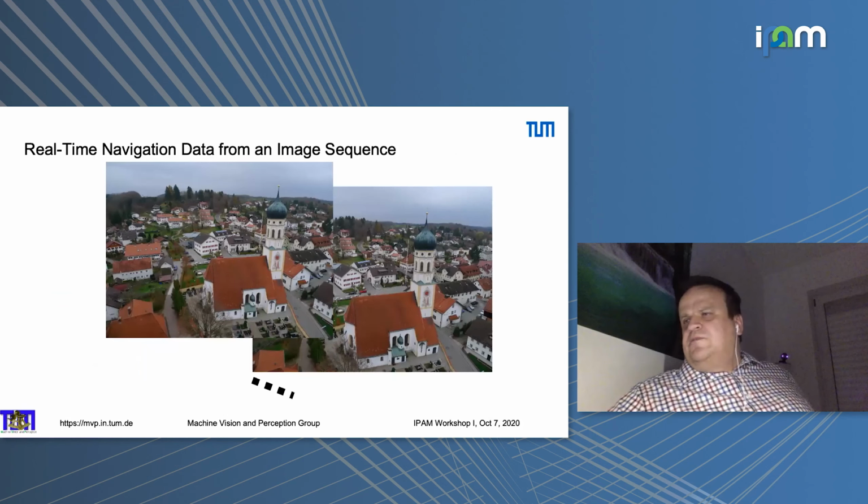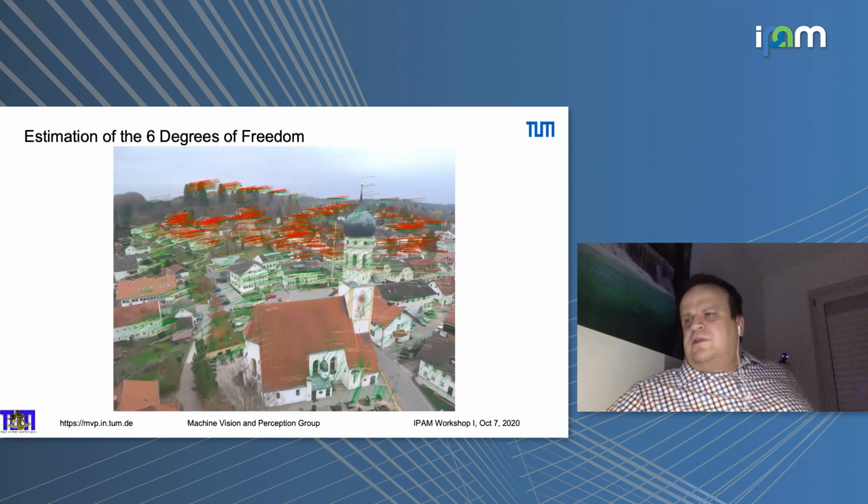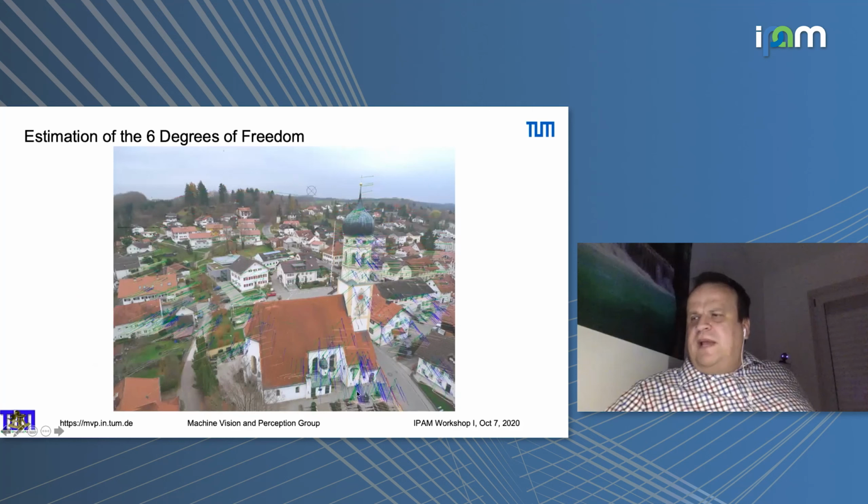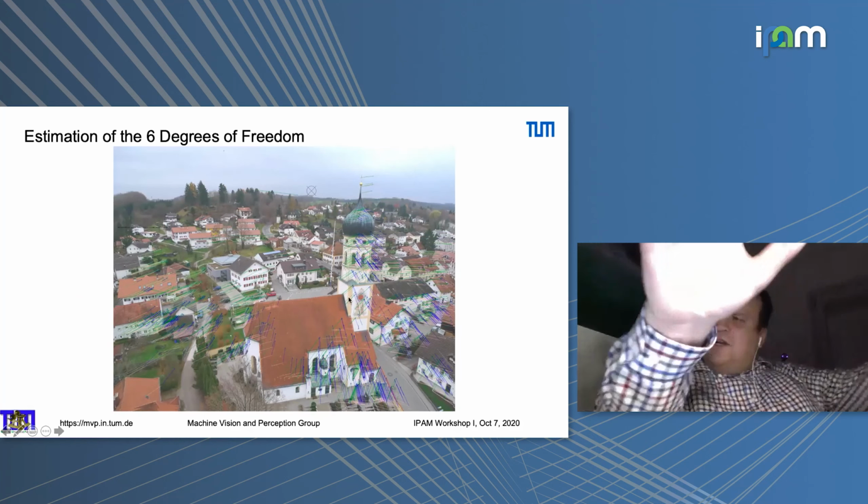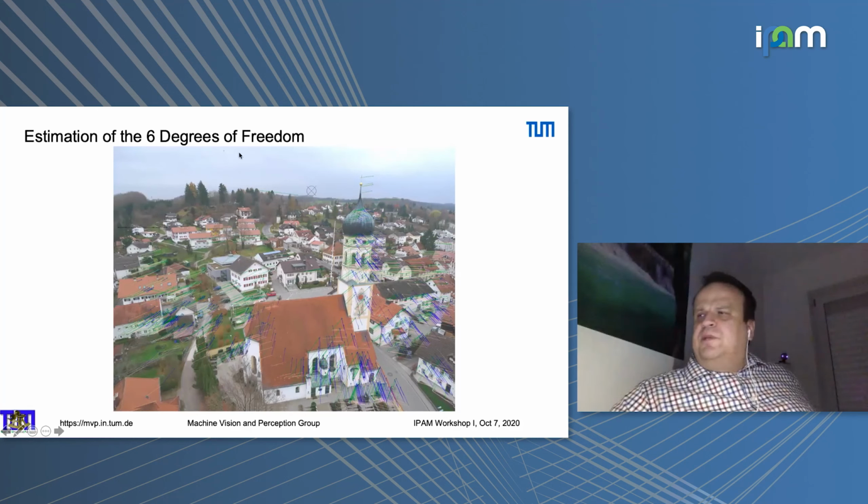So what we did was acquire 60 images with the camera, by telling it to take an image every 20 seconds. And now we use this optical flow system. The green lines, I hope you can see them a little bit, are optical flow lines. And from the calculation I just explained, the system could recover the blue flow, which is just the translational motion the drone was doing between 2 images. And the intersection point was here.